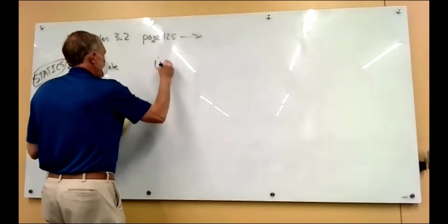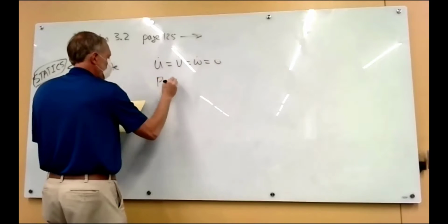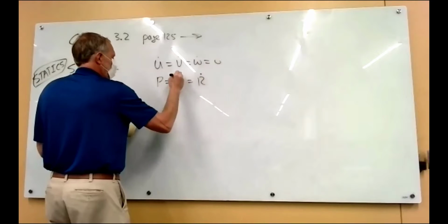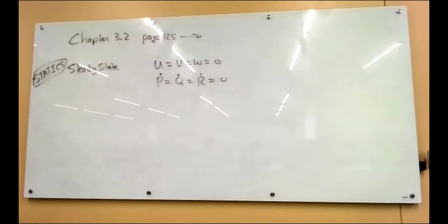And that's because we have zero accelerations, both linear and angular. In fact, that's how we came up with the steady state equations of motion. We went to the full-blown nonlinear equations of motion and made that happen. And then on top of that, we would say, okay, for rectilinear flight, P, Q, and R are 0. For turning flight, Q is 0. And for a pull-up, P and R are 0. So we specialize different cases.